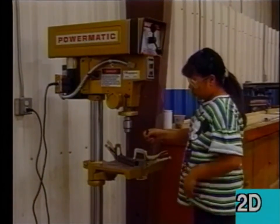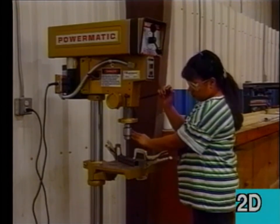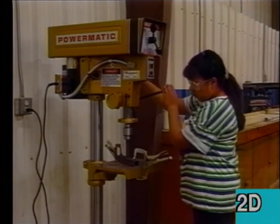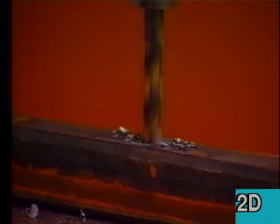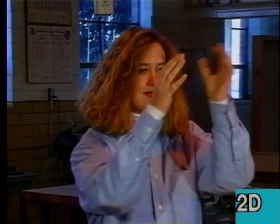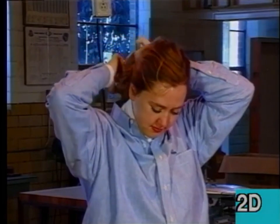The way your clothes fit can present another hazard. Do not wear loose-fitting clothing that can get caught in moving machinery. For instance, unbuttoned shirt sleeves could get caught in the drill press, which could cause serious injury. Ties should not be worn at any time. Long hair can also be a hazard in the shop. If you have long hair, wear it under a cap or tied back so it doesn't get caught in moving machinery.